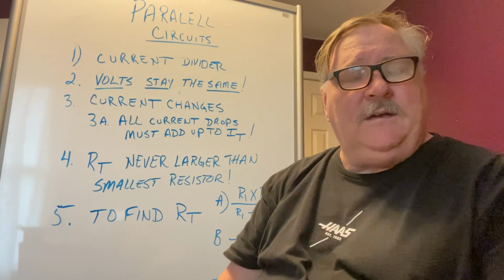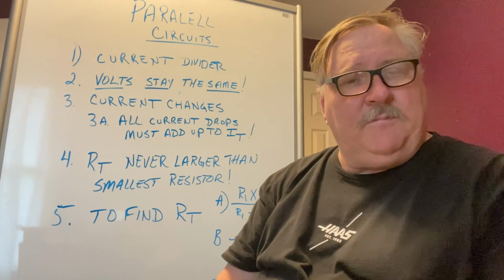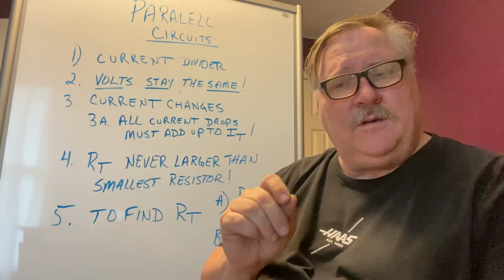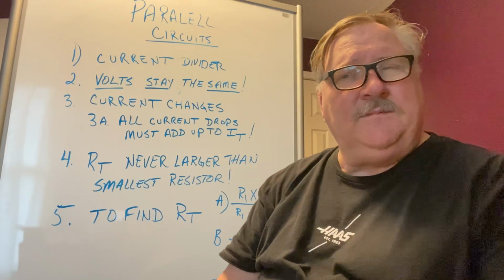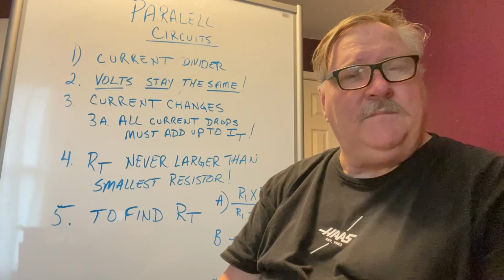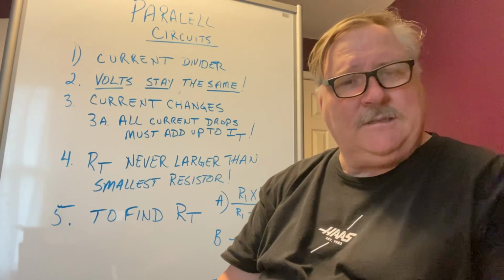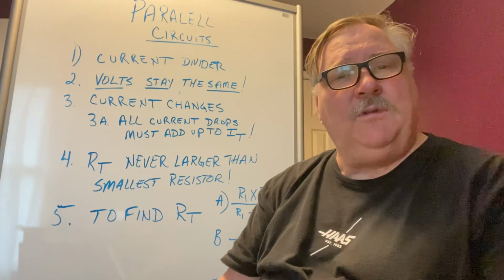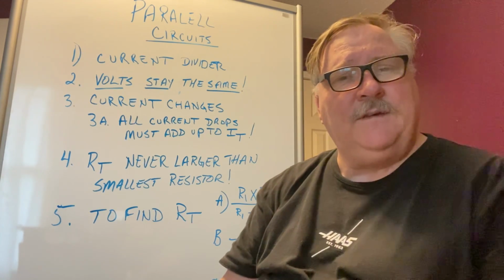But your headlights are in parallel. Your taillights typically are in parallel. And you're getting 12 volts throughout that. But the current is what gets divided throughout that. Sometimes you might find some problems when you start hooking up your speakers and some extra, bigger amplifiers and stuff like that, and it doesn't work right. That's because you're starting to stress the system. You're dividing and dividing and dividing until a point where there's nothing left to divide. There's not enough current in there.